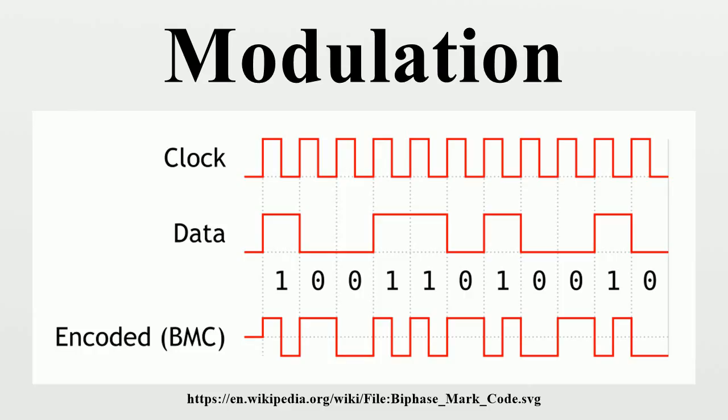In music synthesizers, modulation may be used to synthesize waveforms with an extensive overtone spectrum using a small number of oscillators. In this case the carrier frequency is typically in the same order or much lower than the modulating waveform. Analog modulation methods. In analog modulation, the modulation is applied continuously in response to the analog information signal. List of common analog modulation techniques.